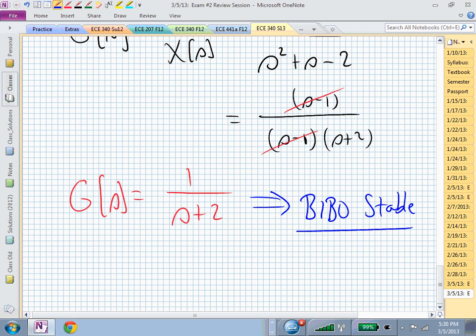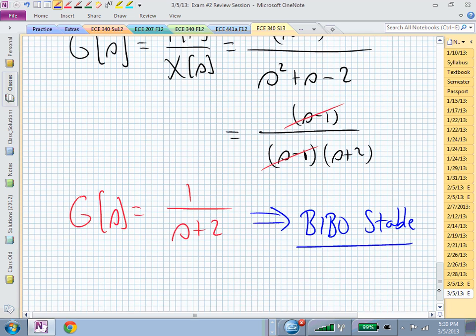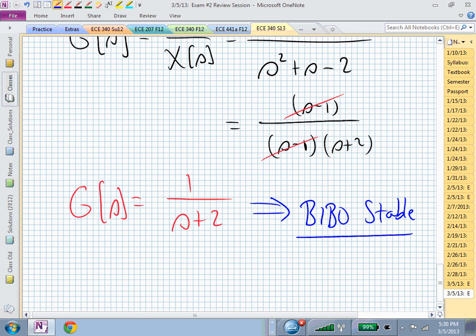Question? So we can't get excited the way maybe go non-linear off the rails or anything like that. From an input-output standpoint, this system is theoretically well behaved. As long as no one energizes or puts any initial condition on that unstable pole, then from an input-output perspective, we're okay. As long as you hit it with a bounded input, you're going to get a bounded output.